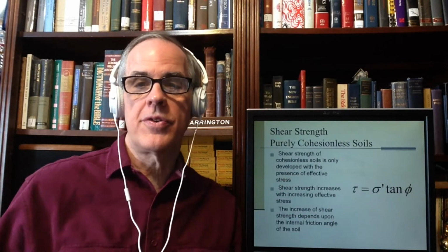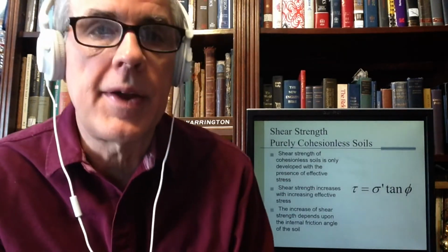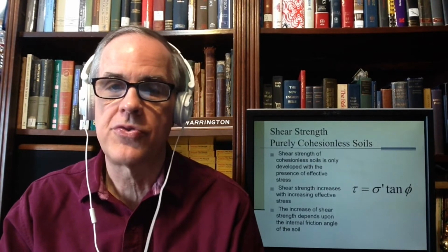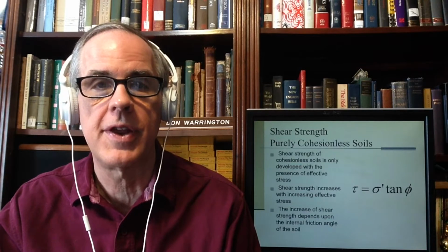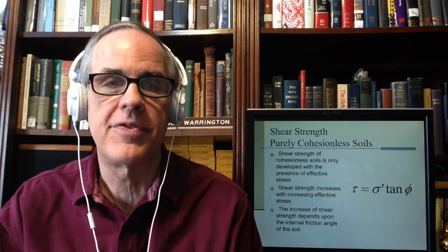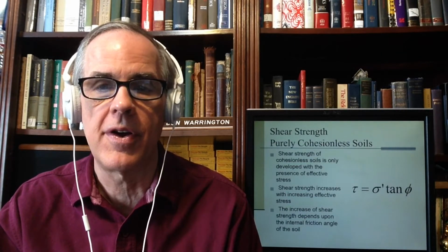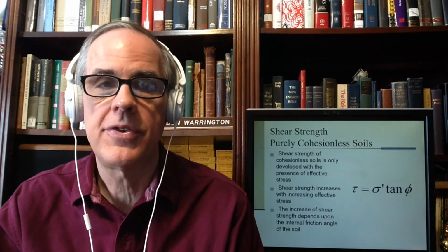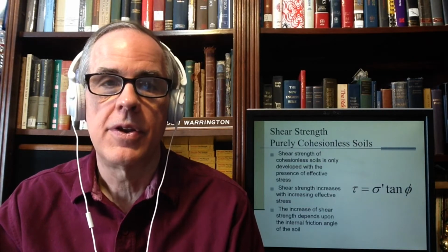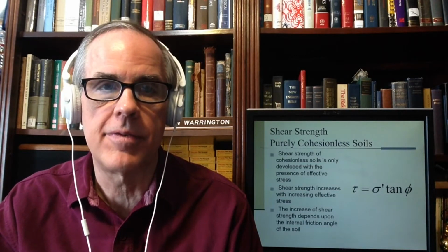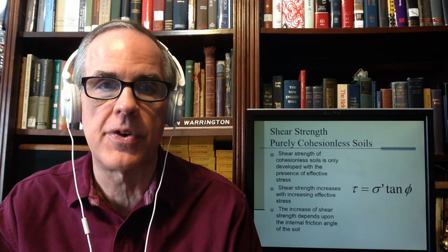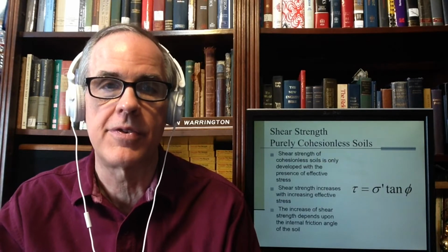For purely cohesionless soils, the shear strength again has no C and is strictly a function of two things: the internal friction angle and whatever confining or effective stress is on it. This is important because a cohesionless soil requires some kind of surcharge or precharge to get any strength to it.